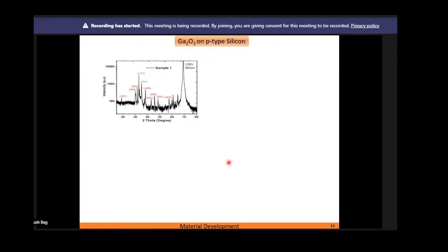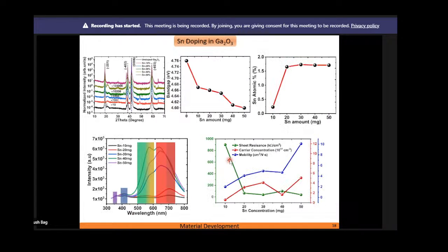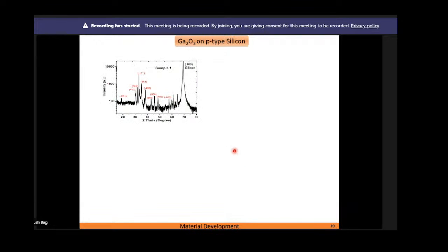So after confirming that, tin doped gallium oxide on sapphire. Again, remember all the deposition here we did on sapphire, that is the substrate. As I mentioned initially also, instead of sapphire, if we can utilize silicon, that could be the best possible thing. Why? Because in existing electronics, mostly you will see silicon. So you can integrate these gallium oxide based devices on silicon and get much more enhanced performance from your overall system. This integration is the most desired integration, but there is a difficulty.